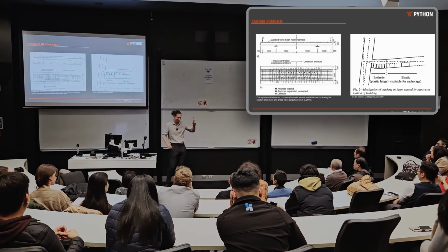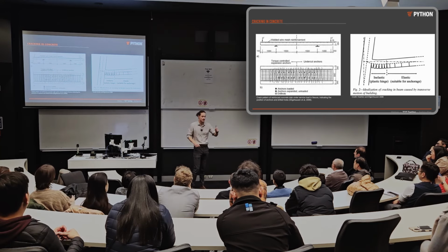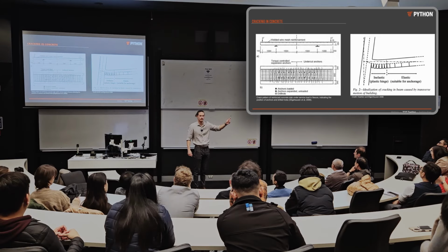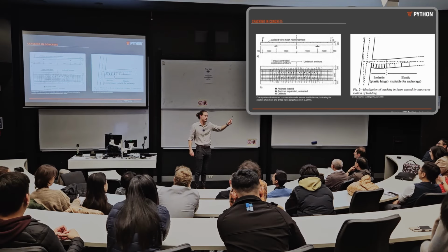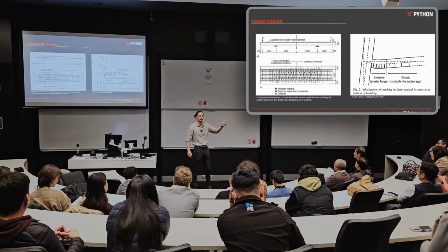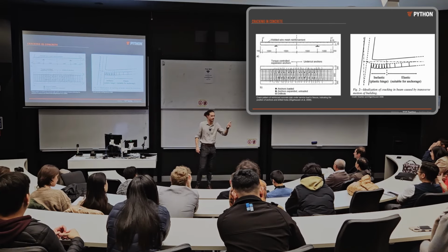One thing that is worth noting is these crack widths were developed thinking about the elastic portion of a beam. The plastic hinge zone is absolutely not covered by a C2 capacity. In a seismic event, we expect pretty severe cracking and damage in a plastic hinge zone, and there is no anchor, to the best of my knowledge, that is at all in any way rated to be used in a plastic hinge zone under a serious seismic loading.